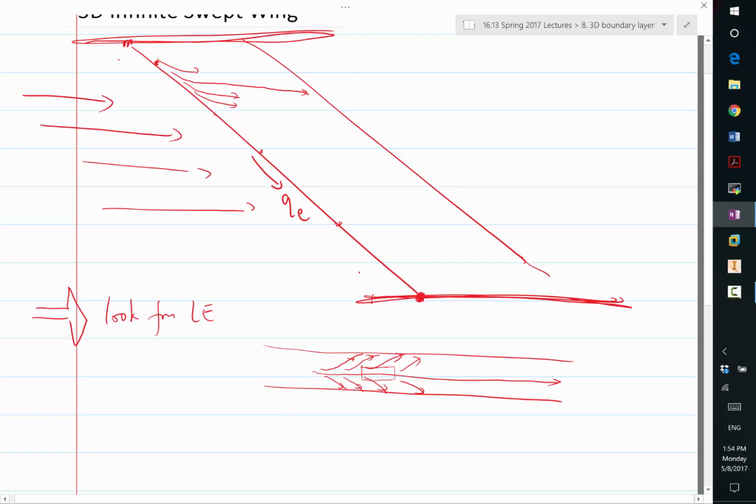And you can use the divergence theorem, because whatever flow goes in here also comes out from the right. But on the top surface, all the streamlines go out. On the lower surface, all the streamlines also go out, right? So that means inside the leading edge, there is strong divergence of velocity. And the lateral dilatation effect actually makes the boundary layer thicken slower than usual.